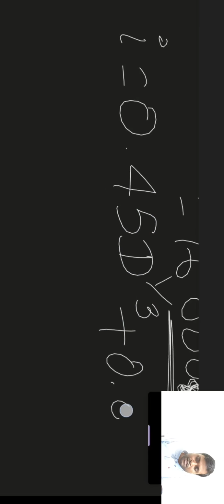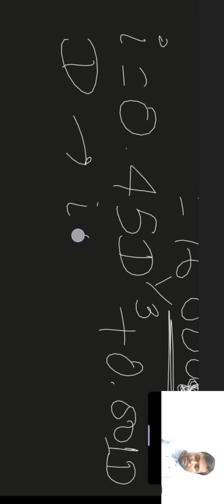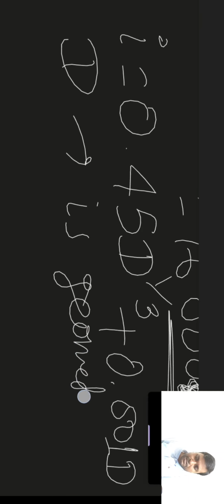Now we have been using i frequently, but what this i is, we have to understand. According to ISO 286, i is 0.45 d to the power 1/3 plus 0.001 d, where d is the geometric mean diameter. Now what is the geometric mean diameter? It is the geometric mean of two values. Then what are those two values?